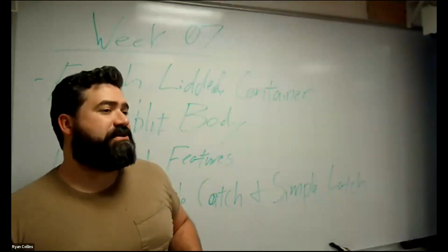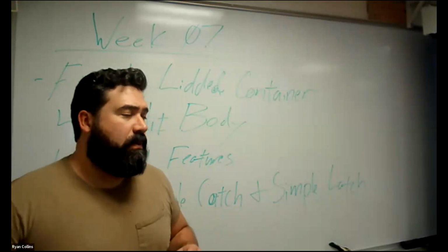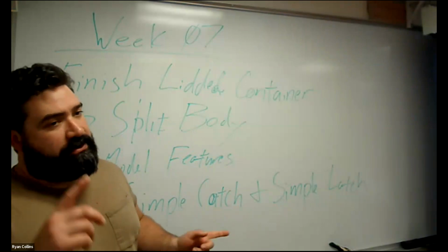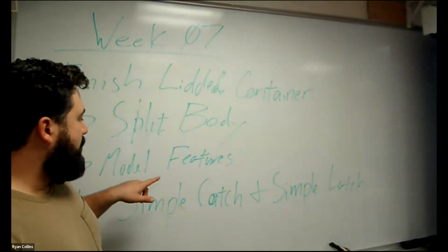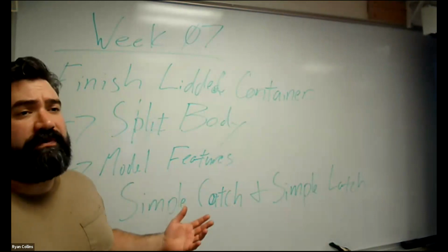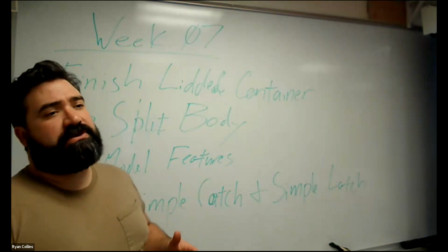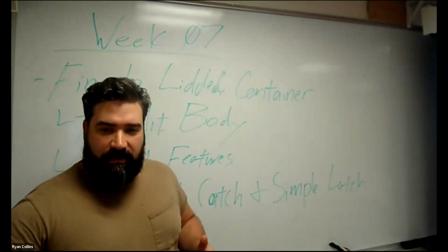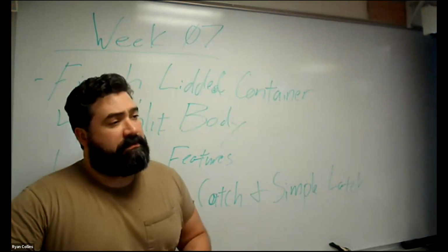All right, tonight we're going to finish up modeling our lidded container. I want to show you a few things, mainly using the split body tool for shrinking that threaded rod we brought in, as well as some other modeling features for the assignment, just giving you some different options. And then I also want to show you a couple of different example options for ways to make this printable, make this more accessible.